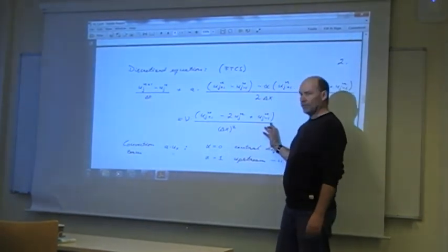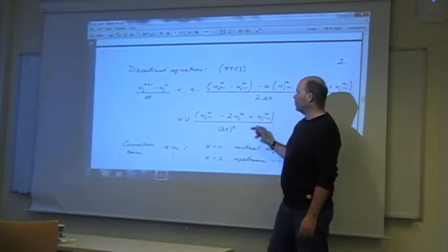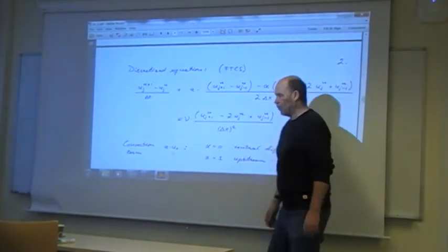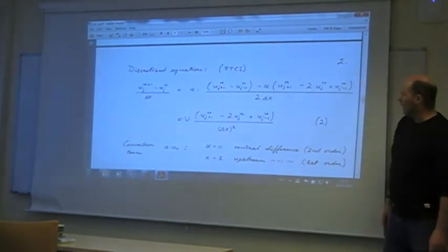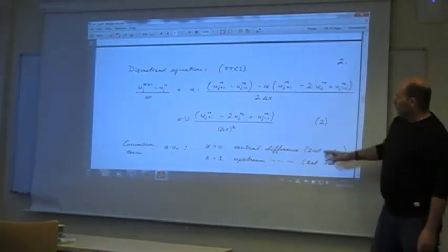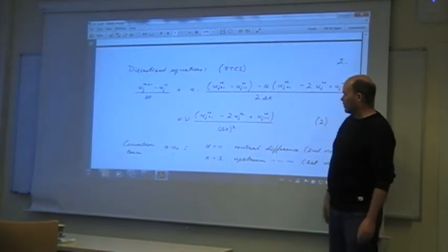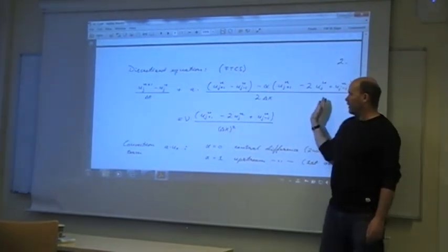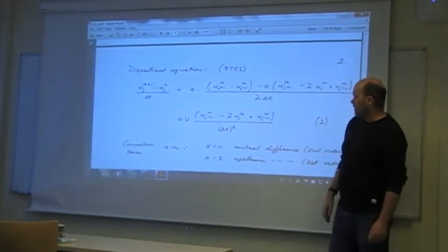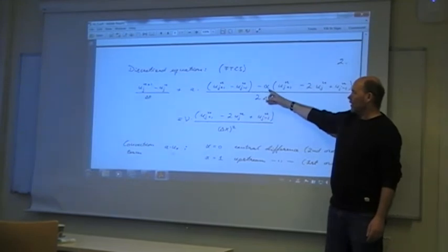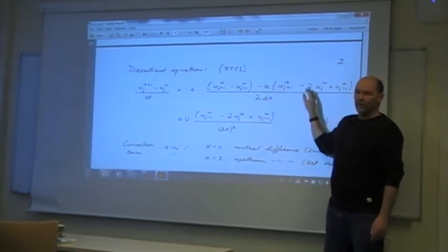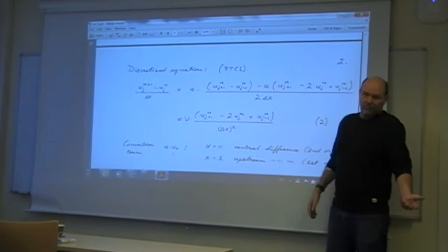That's just a double derivative. You don't have any upwind direction here. You need a velocity in front before you can talk about upwind speed. If you choose alpha equals 1, well, then with a little bit of algebra, you will see this one will be the first order upwind scheme. And then of course you could choose alpha 1/2. Then you have 50% of each. That's a hybrid scheme. That's also possible.